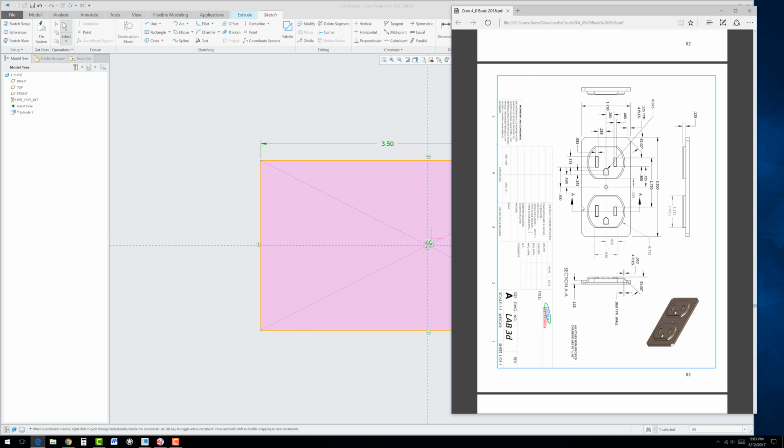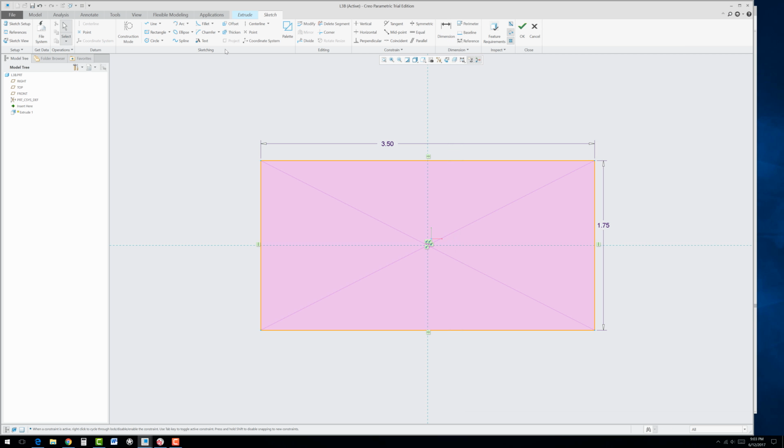Okay, so now we're going to go ahead and we could put the chamfers on. They're 45 degrees by 0.125 if I recall. Here, let's see. No, that's the typical. Yeah, 0.125. Okay, so we could use the chamfer tool here and put those in. Click here to here. And we'll go ahead and put those in here.